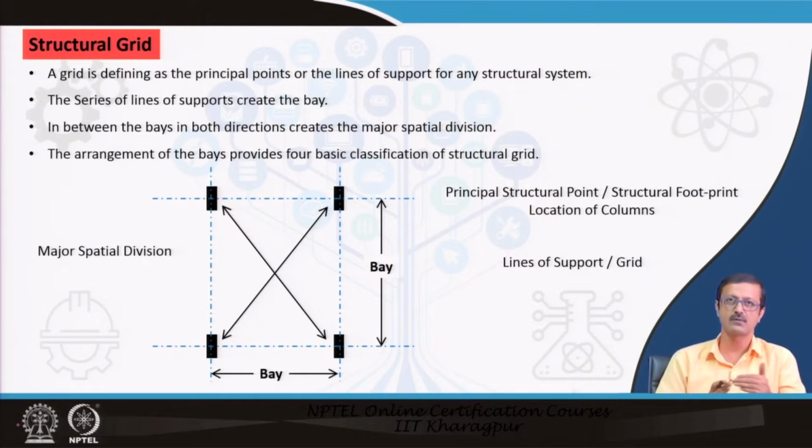If you increase it, then there will be some changes in the structural geometries. Sometimes it may be permitted, sometimes it may not be permitted. Why not permitted? Because if it is increased, the span is going to increase, which may create huge bending stress, huge deformations and deflections. So, the structural engineer may not allow that. So, you have to have a tentative idea of what the grid size should be and how it is going to be functional with your habitat or your activity.